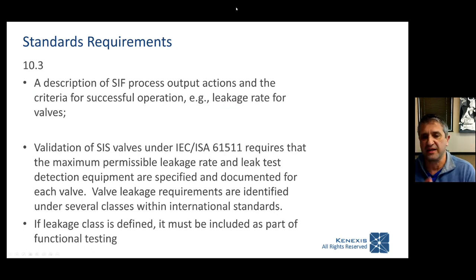The worst method is to go to clause 10.3, take that bullet point list and turn it into a fill in the blank table on a safety function by safety function basis. That is an absolutely horrible way to prepare safety requirement specifications. We do not recommend it. We have a different approach I'll get to toward the end of the presentation when I get into workflow.